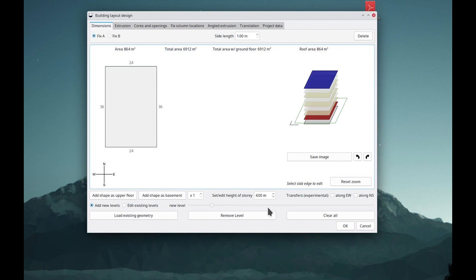However, we know, because we've done good academic studies, that this will yield a very inefficient project. We find, in fact, that typically, even keeping the exact same layout, just choosing the right decking can save perhaps 25% of the carbon and perhaps up to 15% of the cost, give or take. Of course, if you then adapt the layout a little bit, the gains can be as high as 50% of the carbon and 20% of the cost of a frame.